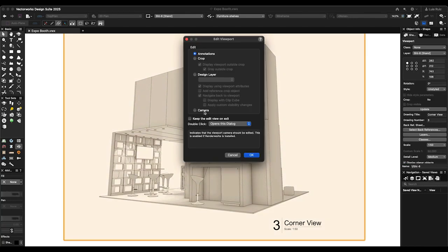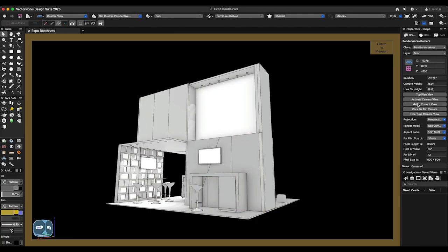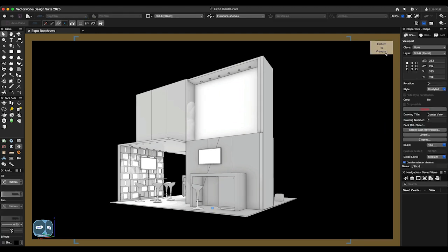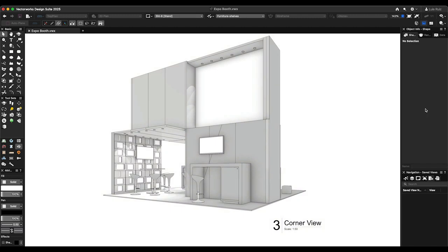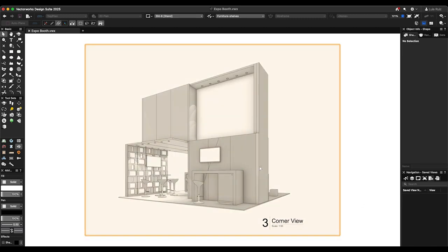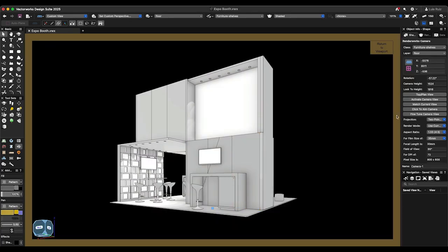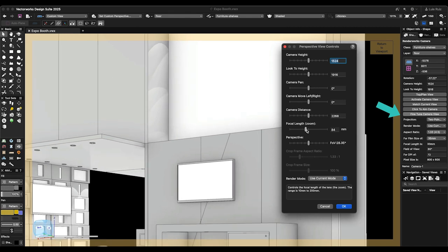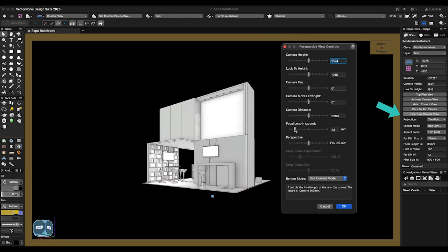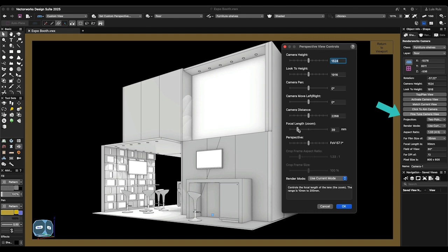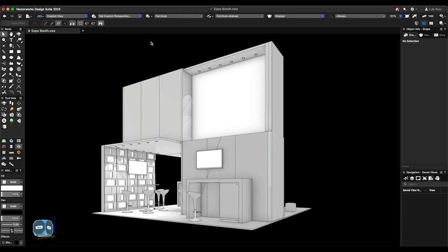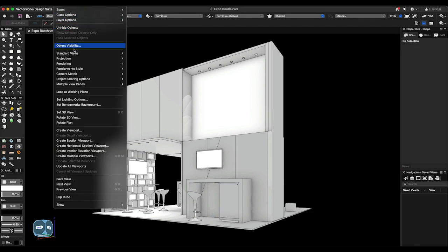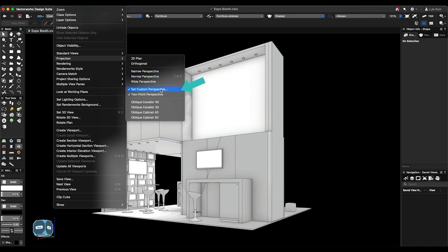To create high-quality renderings, use a Renderworks camera object for better results. You can easily change the preferred projection of these cameras directly in the Object Info palette by selecting the desired projection mode. With cameras, you can apply various camera effects and control the field of view. You can access the settings for field of view through the Object Info palette, or the camera object, or directly within the design layers. In design layers, use a custom perspective projection mode combined with a 2-point perspective projection.